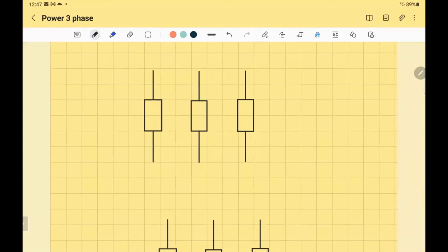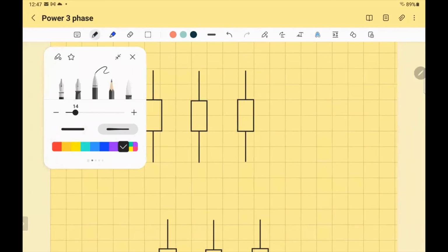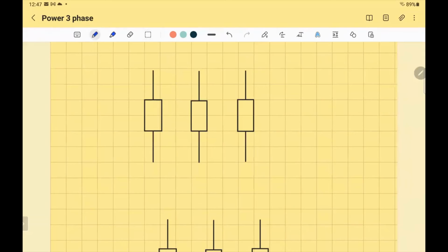Each has a beginning and end. If you say that is A, that's A dash, B, B dash, C, C dash. Even when you go to industry, you will find motors have the terminals exactly like that. They have a switch here, then you connect it in star. You just connect this one by this one, and then you just make a short circuit on the end of the three. You got a star.